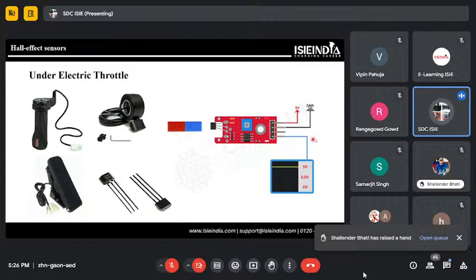And this response goes to the controller, and the controller, as per that only, increases the voltage, current, and frequency delivered by the power electronic converters. So we are giving the input power supply from the battery through the BMS to the controller, along with some manual responses. As per that only the vehicle is going to run, right?